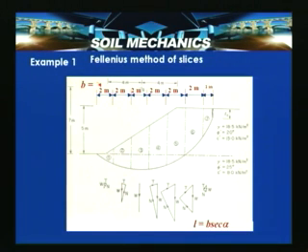Now, let us look at an example based on whatever we have discussed about the Fellenius method of slices, Bishop's method or Swedish method of slices. Here a slope with a certain cross section is shown, with pore water pressure data, and this is the location of the tension crack, which is based on 2 C by gamma, estimated here. So, this is the tip of the tension crack.